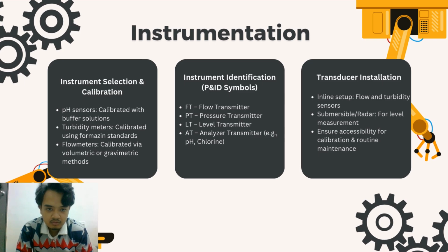So next, for transducer installation, the first one is inline setup for flow and turbidity sensors, and then submersible or radar for level measurement. And then the last one, we need to ensure accessibility for calibration and perform routine maintenance.